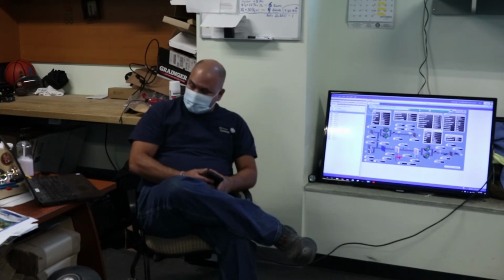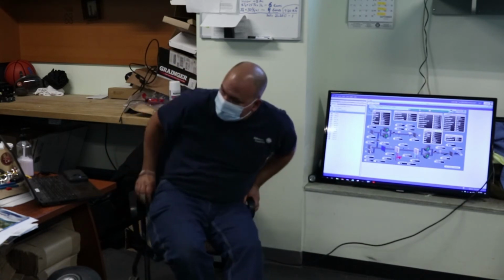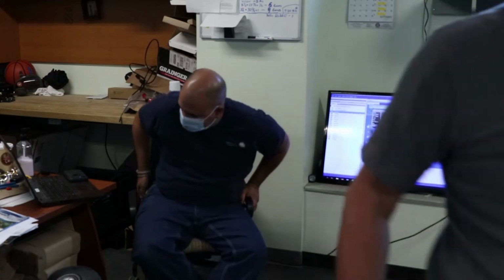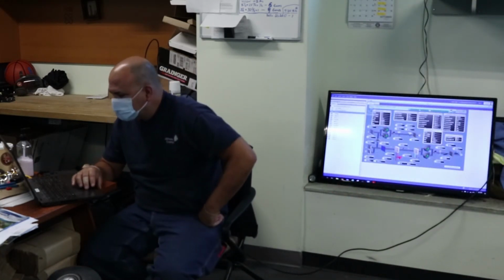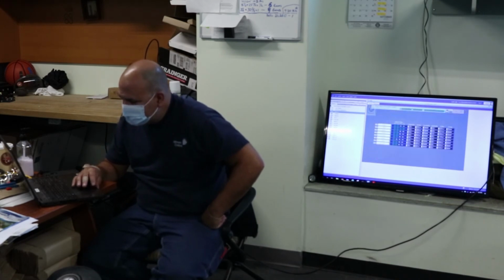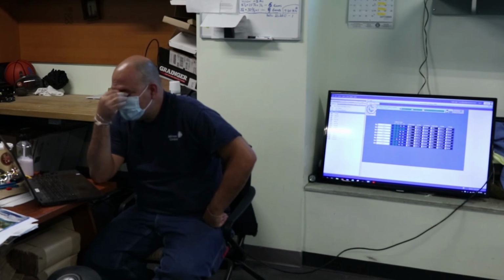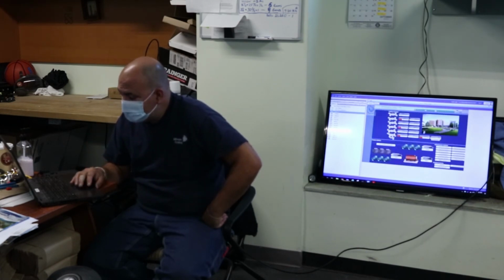Remember the little post-it notes we had on the Honeywell panel? On the Honeywell screen, click on these little notepads down here. I'm gonna put boiler one supply sensor, no signal. And we'll leave it there to remind Phil when he sees it, okay? Yeah, well, you know, it's good to show it to him if it's in his face.